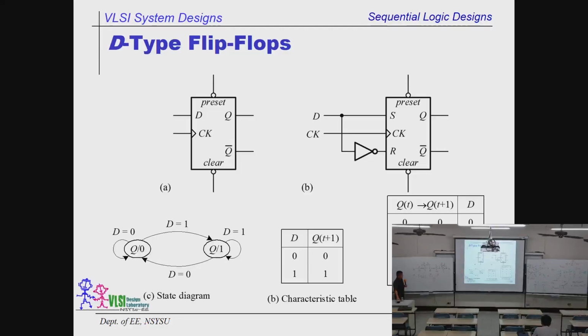All right, and this is a standard figure for the D-type flip-flops. Because it is edge triggered, I have to highlight, show you that there is a triangle over there to tell the reader this is edge triggered. It is not level sensitive. So if there is no circle, that means it is positive edge triggered.